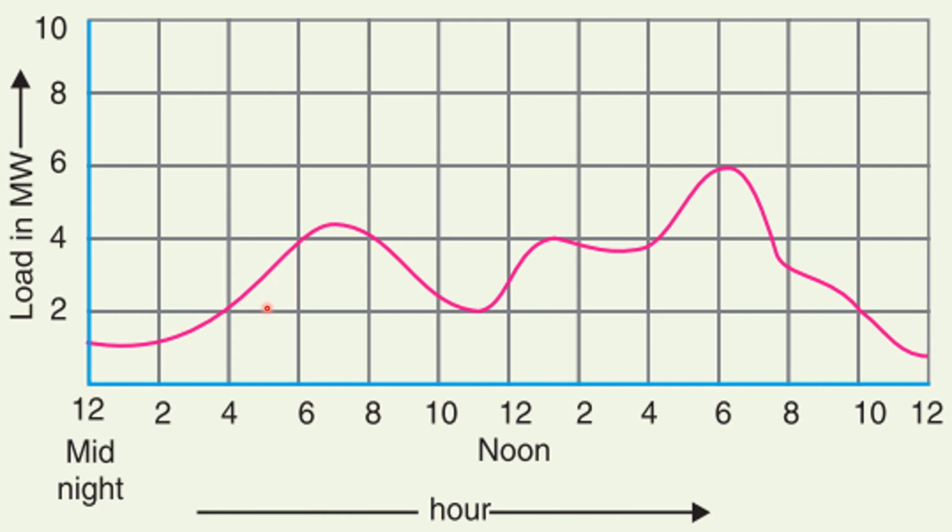After that, you can divide that megawatt hour energy consumption by the total number of samples which you took, and that will give you the average load in a day. So that is one way to do this, and that is an approximation, obviously. But if you take enough samples, that approximation can become very accurate.